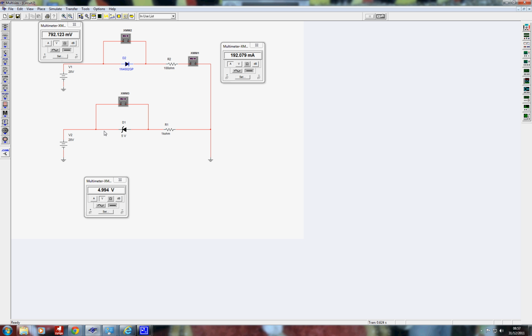This makes Zeners very useful in circuits such as voltage regulators, where we need smooth, stable and regulated power supplies to run things like computers and microcontrollers and logic circuits. And that's what you're going to be dealing with when we're looking at the circuit for Electronics P1 and P2, which shows us how we can go from AC to DC to regulated DC.